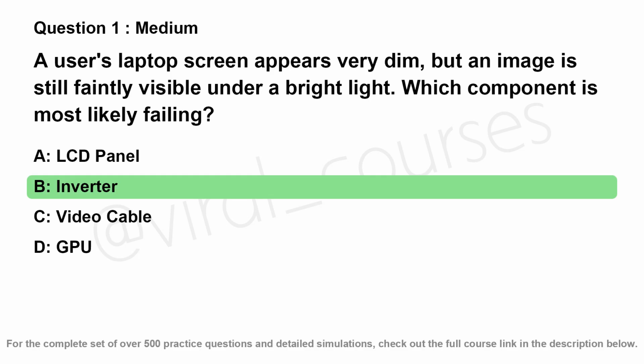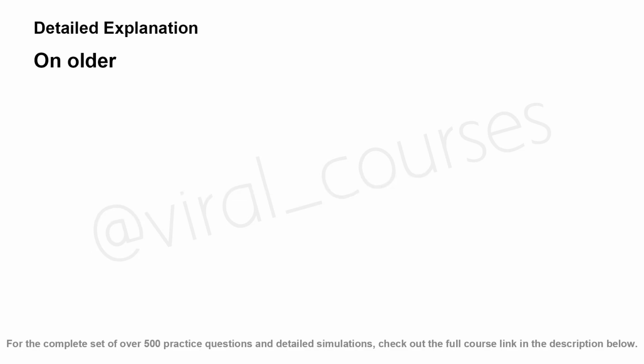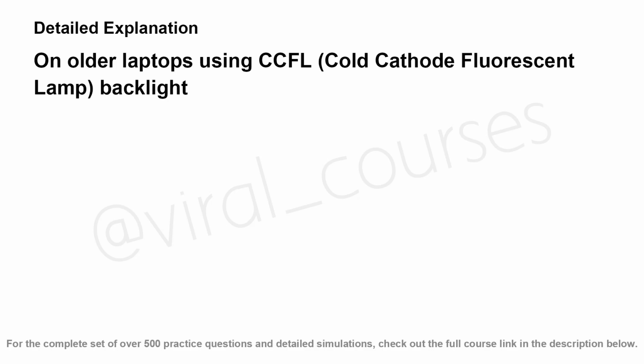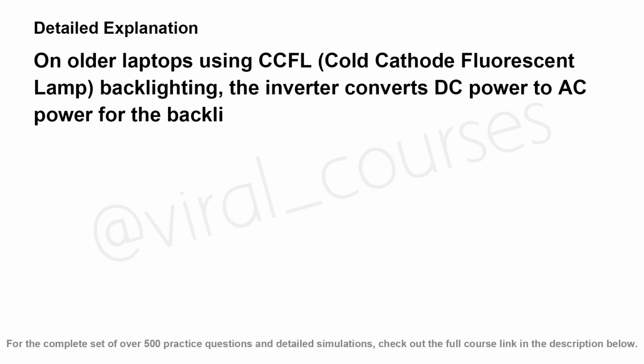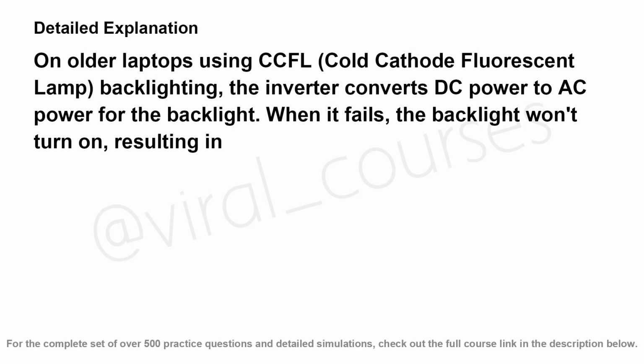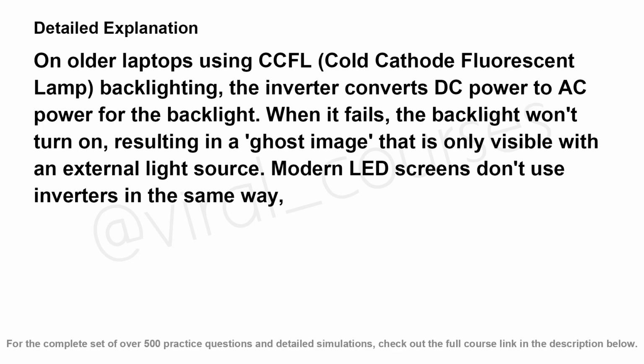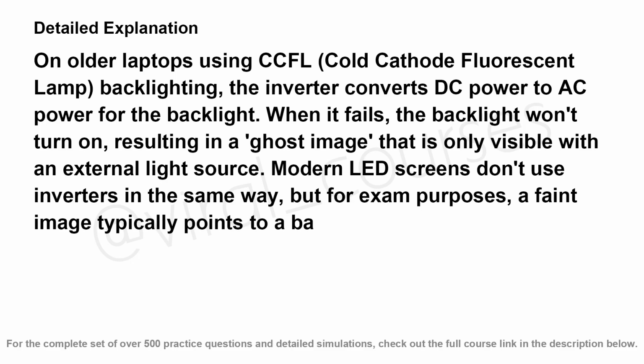The correct answer is B. On older laptops using CCFL, cold cathode fluorescent lamp, backlighting, the inverter converts DC power to AC power for the backlight. When it fails, the backlight won't turn on, resulting in a ghost image that is only visible with an external light source. Modern LED screens don't use inverters in the same way. But for exam purposes, a faint image typically points to a backlight or inverter issue.